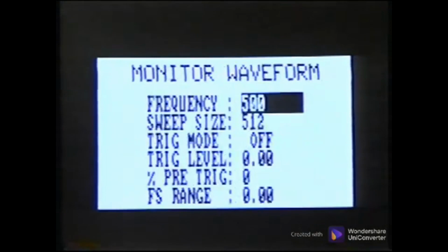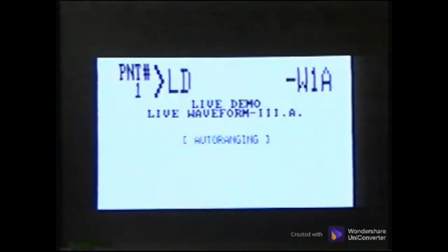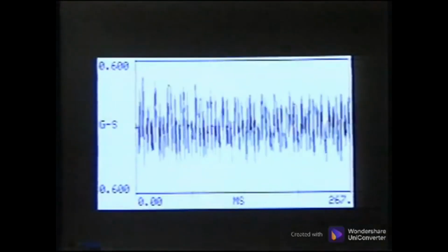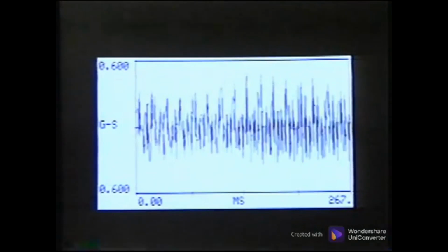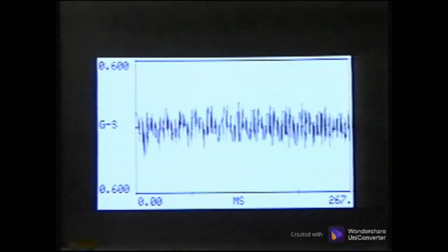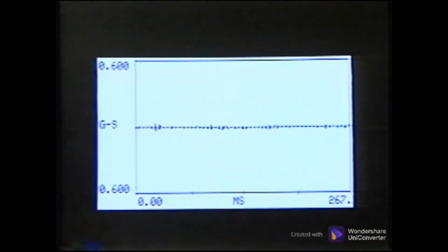Here we are using a single channel analyzer to monitor the waveform. Set the maximum frequency and sample size to capture the data, being sure that the sample time will not cause the shutoff to be missed. The fast update rate of the waveform helps ensure capturing the change as the machine is shut off. Notice the drop in amplitude as the electrical energy is removed from the waveform. This indicates that nearly half the energy is attributed to electrical events.